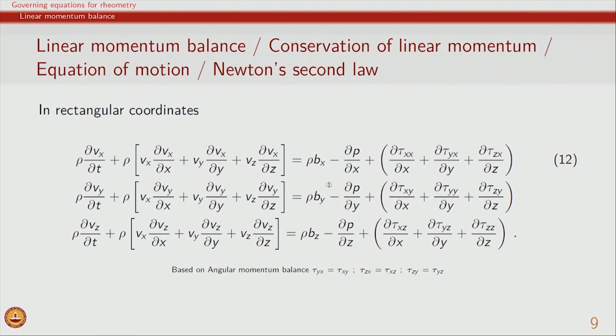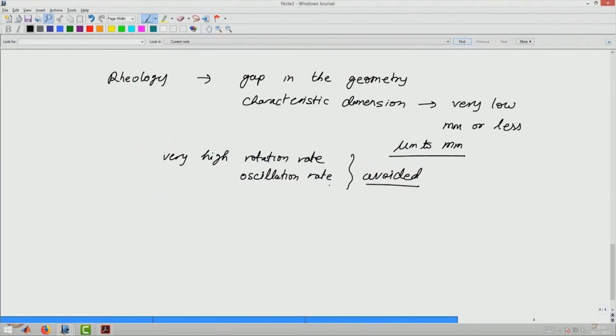So, based on these different terms which are basically related to force balance, we can try to analyze a given rheometric flow. So, we can begin with a simple example that we have seen many times, which is the case of parallel plate flow, where we have the coordinate system y and x, and what we have is the top plate moving with a certain velocity, and of course, instinctively we have been drawing the overall velocity profile which is linear.